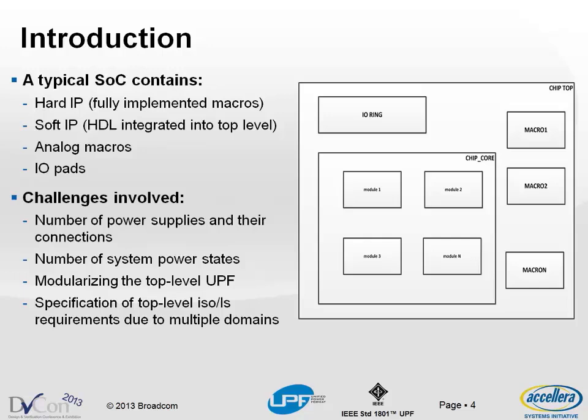Now, if you translate that into a SoC, you just have an explosion in the number of system-level power states. And then it also becomes a problem of how do you organize, how do you modularize, how do you sort out your UPF. And just like we have problems with HDL, where you have multiple files and you partition it into different files, we deal with the same sort of database management problems with UPF. And finally, when you want to talk about strategies, where to put isolation, where to put level shifters, and going into the details of implementation, that question shows up at the top level.